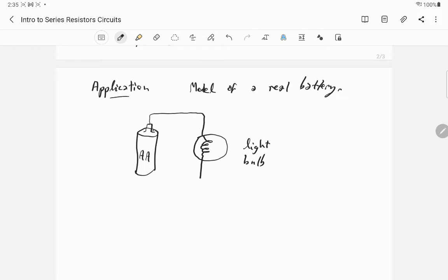Right, to protect the filament, it keeps oxygen essentially away from it so your filament doesn't rust. Okay, so I have a circuit and this light bulb can emit light, right? It emits light, it gets warm, etc. But the other thing is, this is Joule heating. It's because of power dissipated by a resistance, right? It's I squared times R. So it's the power dissipated. It's called Joule heating. It's the way you feel it, there's a warmth.